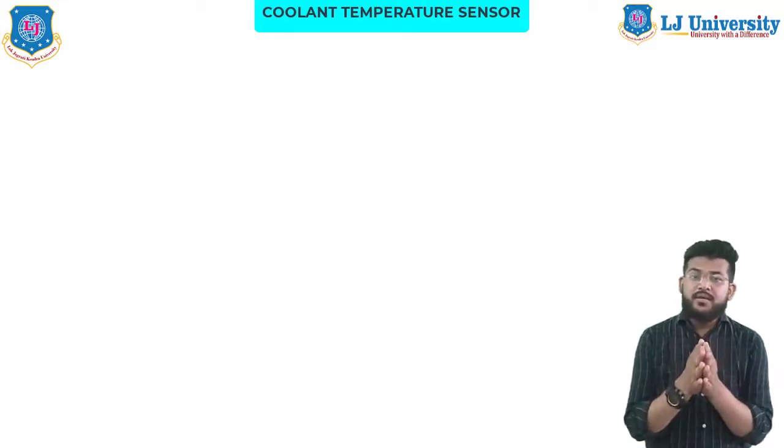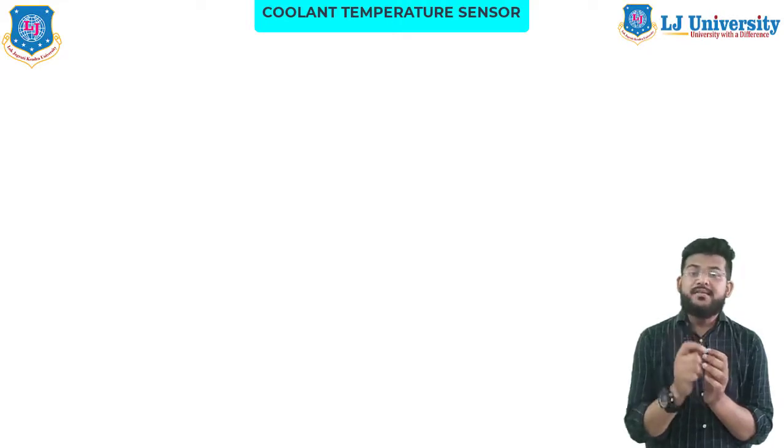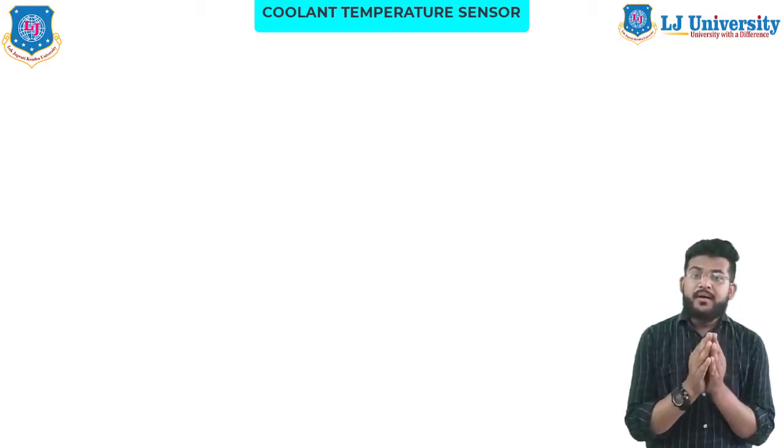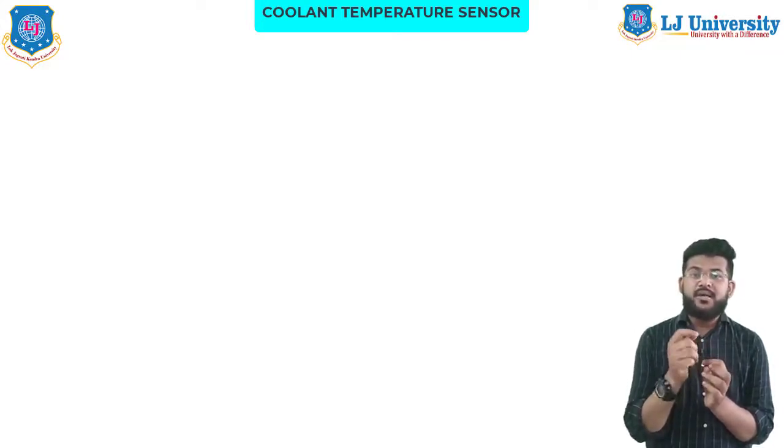The engine temperature sensor connects either to the temperature gauge or to the temperature indicator in the dashboard. In modern cars you can notice that there is no separate engine temperature gauge. Instead there is a tiny light symbolizing the engine temperature, which is integrated with the RPM meter. Upon turning the engine on, the letter C also lights along with the temperature symbol, indicating that the engine is cold. It should automatically disappear once the engine warms up and its optimum temperature is achieved.